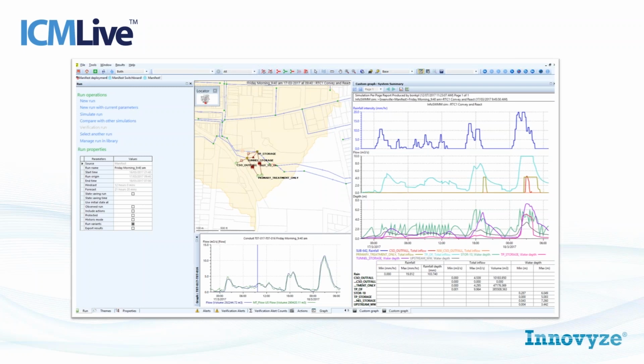Yeah, I haven't really used the time series database functionality much, but I can see some amazing opportunities for it. Even things as simple as you want to do some maintenance work for a part of the network, and you can tell your operators how much flow they can expect in the network at that point in time, and therefore what kind of bypass pump size they need. CCTV surveys, you can only have a certain depth of flow in a sewer to actually do those. So if we can understand what the depth of flow actually is at any given point in time, we can get the crews out there at the right time of day and then look at bypass pumping if required to do that. There's a lot of guesswork in that area at the moment.